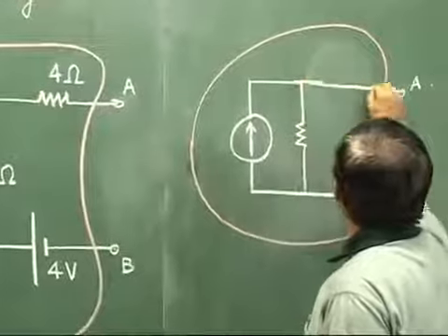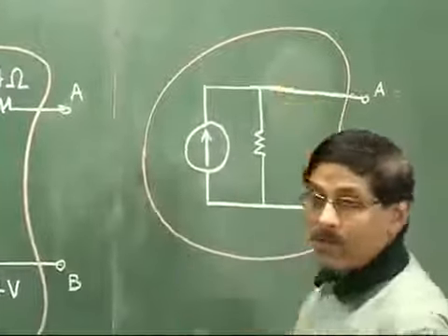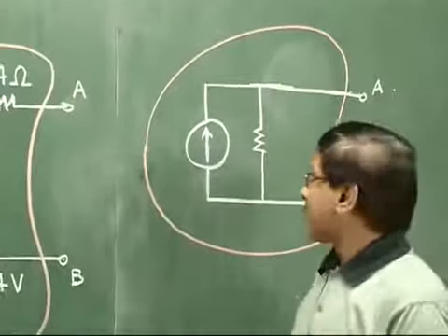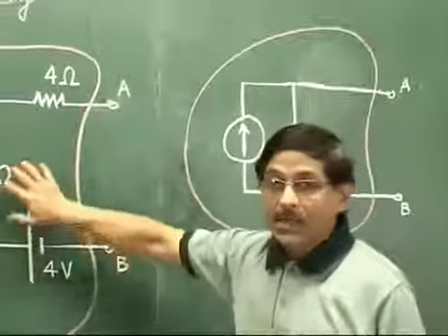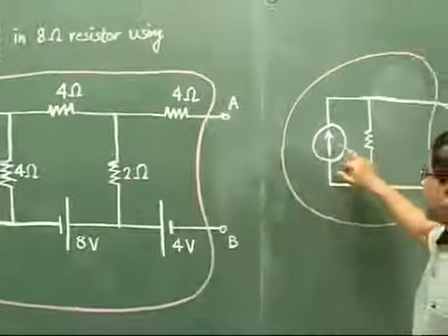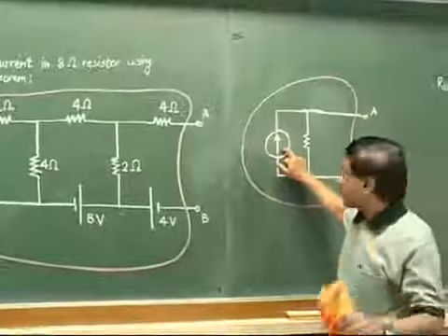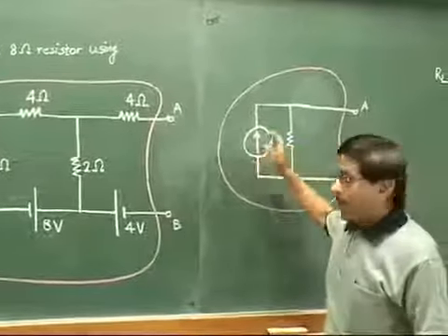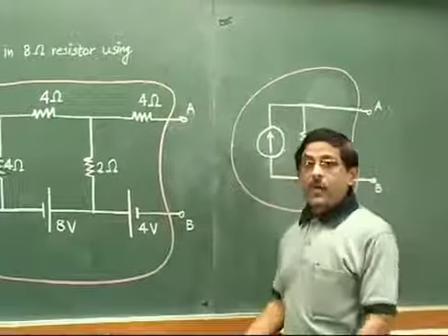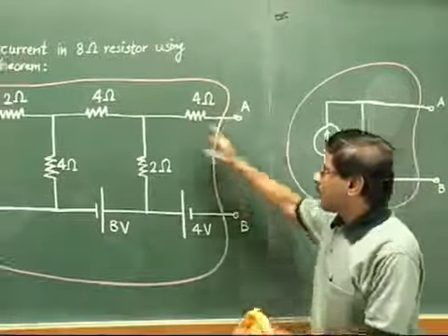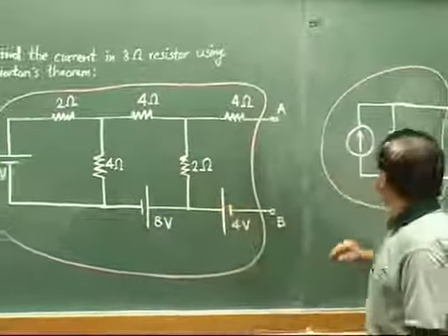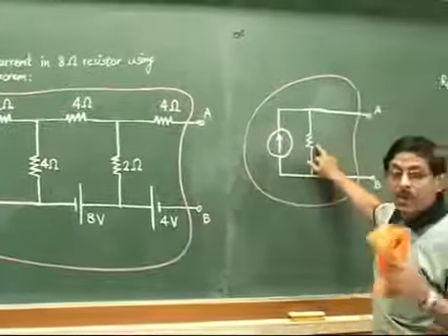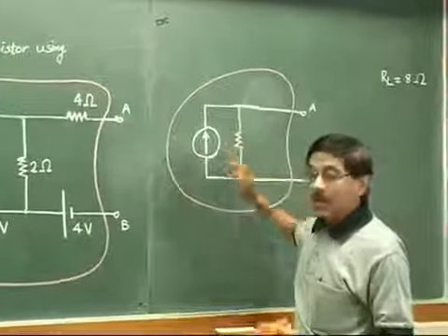This is the central idea of Norton's theorem. Norton suggested that we convert this entire circuit into a single equivalent current source, and represent the entire passive network as a resistance shown parallel to the current source.